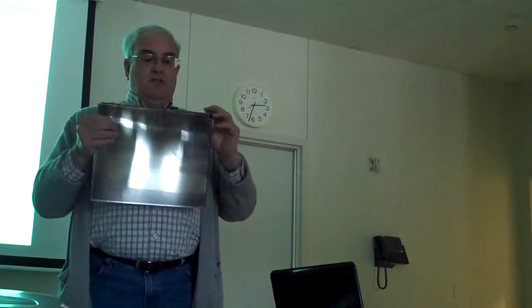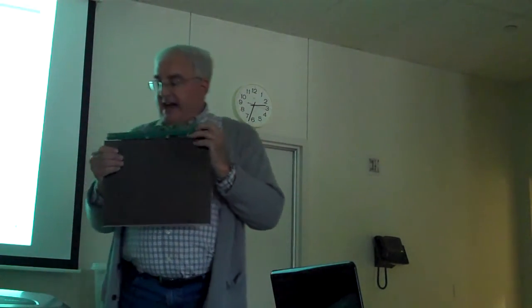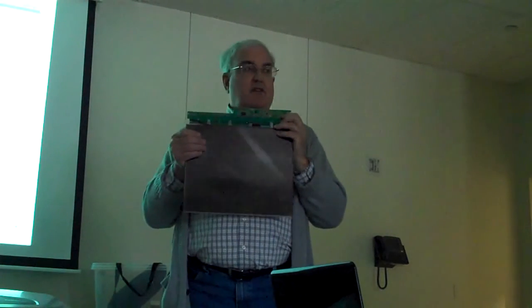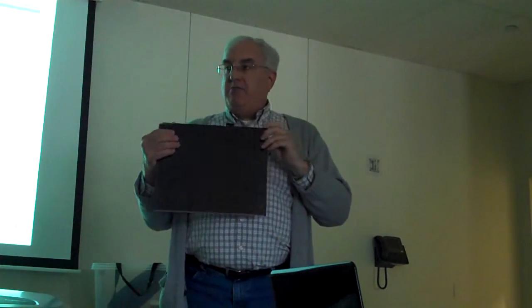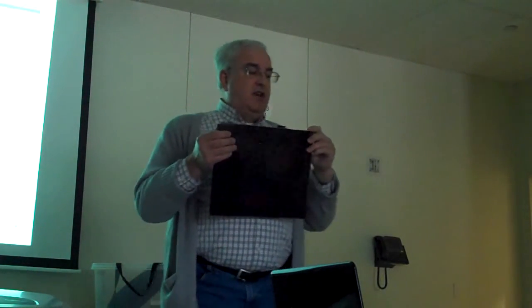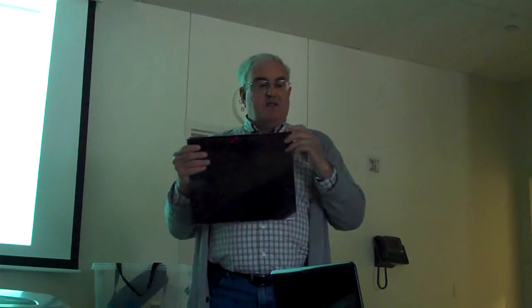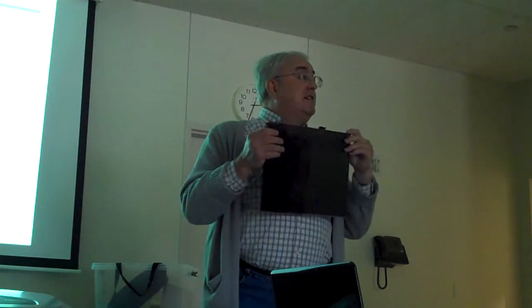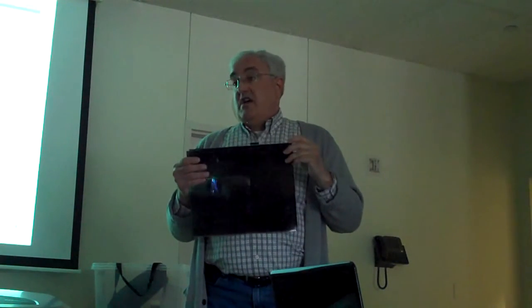But what I'd like you to notice is that the board here is attached with flexible ribbon, and it's what they call tab bonded. Now this means that these flexible ribbons with all of the connectors are not actually soldered on.